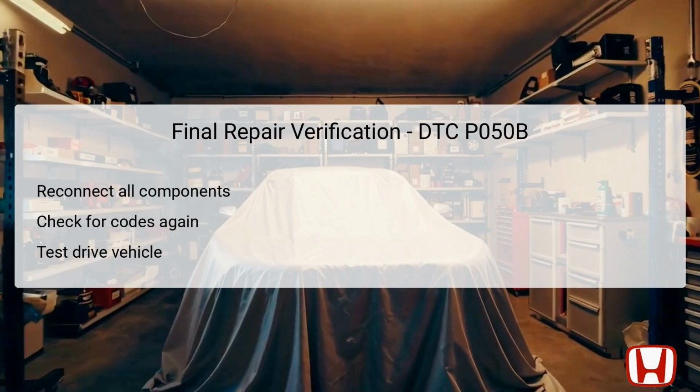After completing all the troubleshooting steps for DTC P050B, it is important to perform a final verification of all repairs made. Start by ensuring that all components, including sensors and hoses, are securely reconnected and free from any obstructions. Use the Honda Diagnostic System, HDS, once again to verify if any new diagnostic trouble codes are present.